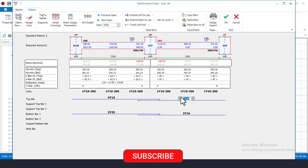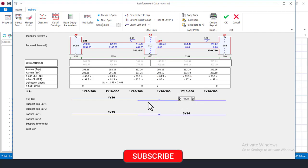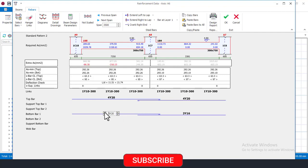And then we increase to Y20, let me see, this will be Y20, yeah. Because of the length of the beam, make here to be 4Y16, and then increase to 4 numbers. Okay, yeah, it's fine, Y20 is okay for that. Everything now looks okay, we don't need a support bar for this right now. Come here and decrease this towards 20 and increase towards 4.